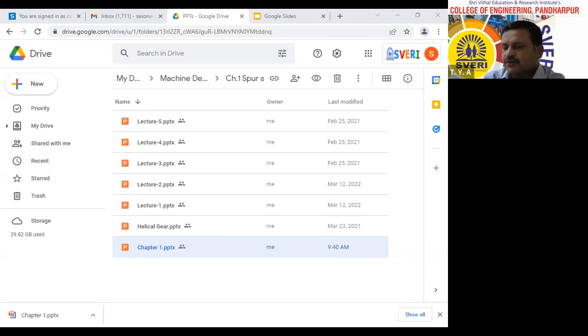Now, why do we have to take permissible bending stress? While deriving Levy's equation, what did we derive? S_B is equal to m b sigma_b into y. That S_B is nothing but the tangential force, P_T. Earlier we derived the equation P_T is equal to m b sigma_b into y.